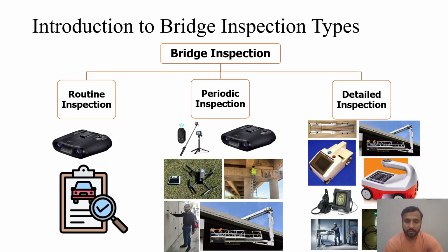Hammers are also used for knocking the concrete surface so that you could get an idea of hollowness or the chances of spalling of the concrete, because the concrete first detaches at the rebar level before the spalling really occurs. Another equipment is the underbridge inspection vehicle, which is a big equipment that is used to have accessibility under the bridge.